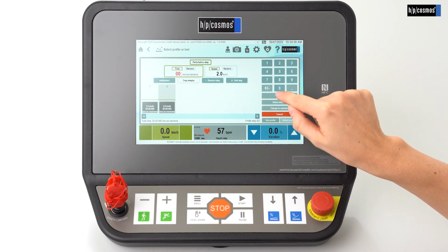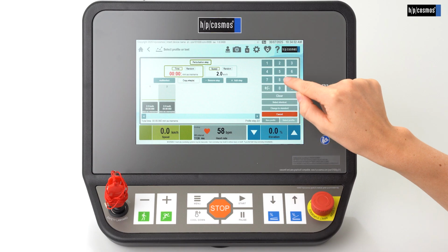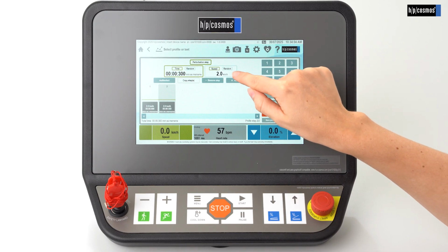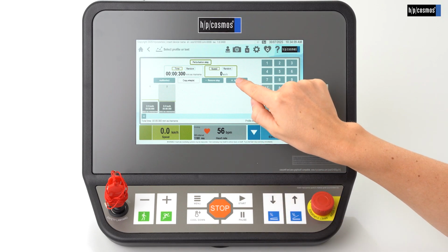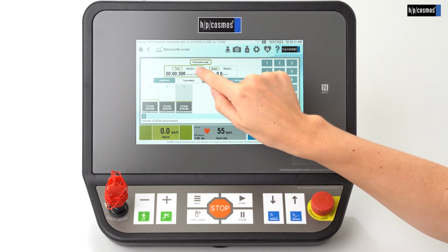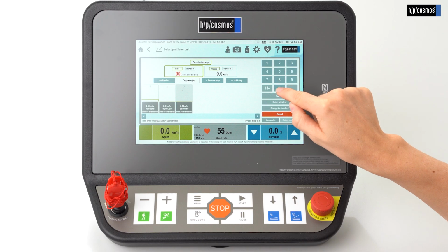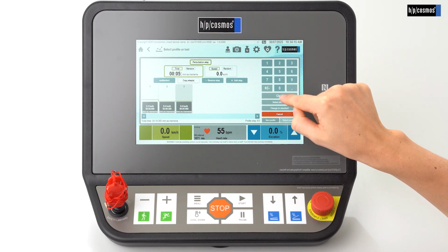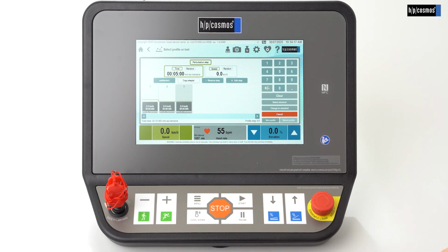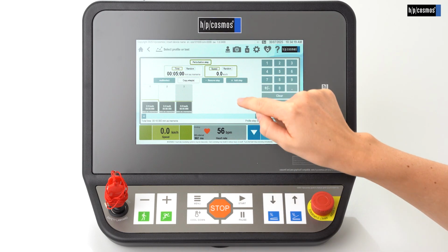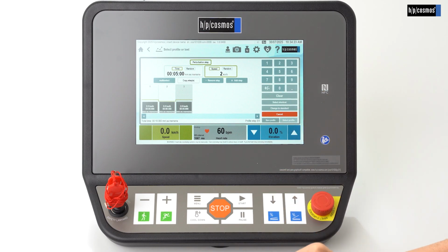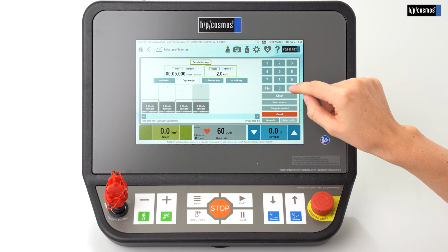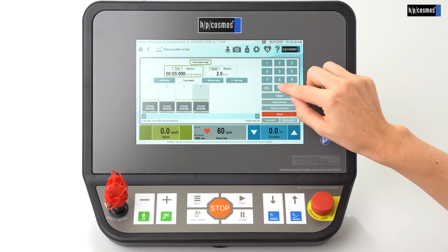Now we create a perturbation step with the duration of 300 milliseconds and a sudden stop of the treadmill, and also add this step to the profile. Afterwards we add the base step with 5 seconds duration and the normal speed. The next step is a trip again, without straight stop but with a short and soft speed reduction.